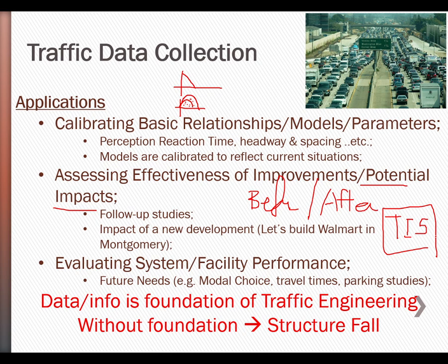You do the four steps we did in transportation: trip generation, distribution, mode split, and assignment. And we figure out how much traffic this new development will have on the road, and whether we need mitigation measures, which means changes in the traffic network around the new development. Will we need to add some signals instead of stop signs? This is called the TIS.